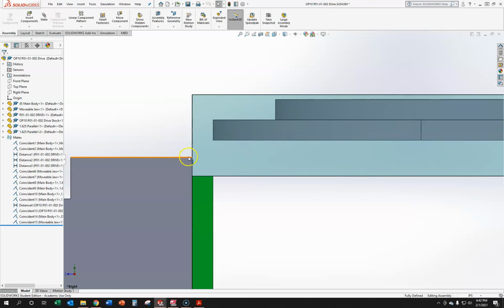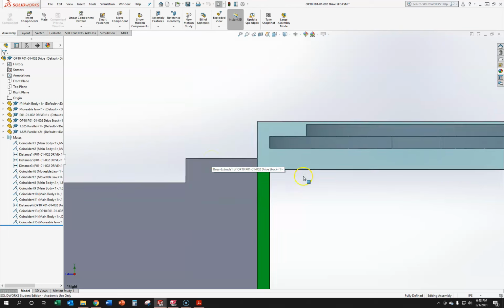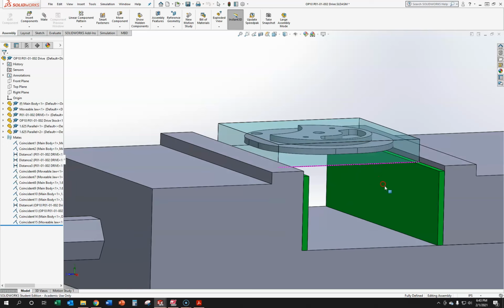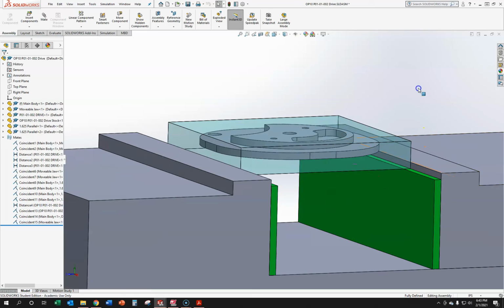And again, the only concern with me is, you see this space here? This is the clearance that we have to machine around it. So in reality, we could probably drop this down another 1/8 of an inch and have more work holding. And that will enable us to sink this down a little bit more and have a more aggressive work holding strategy. An 1/8 of an inch in a vise is not a lot.